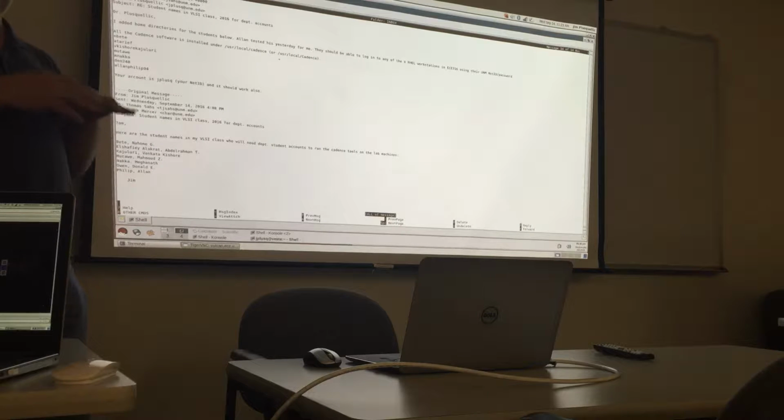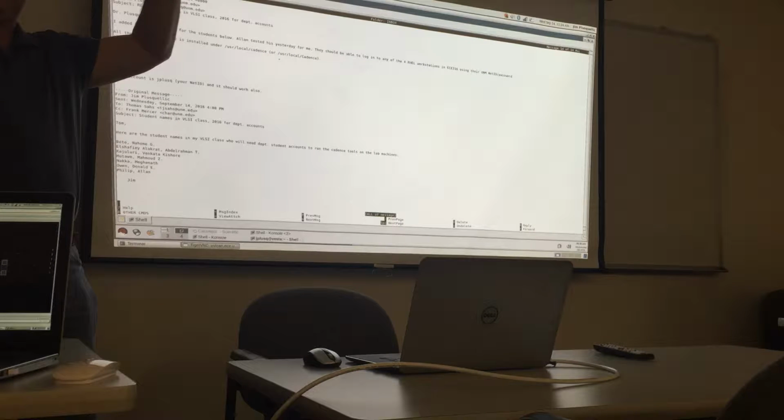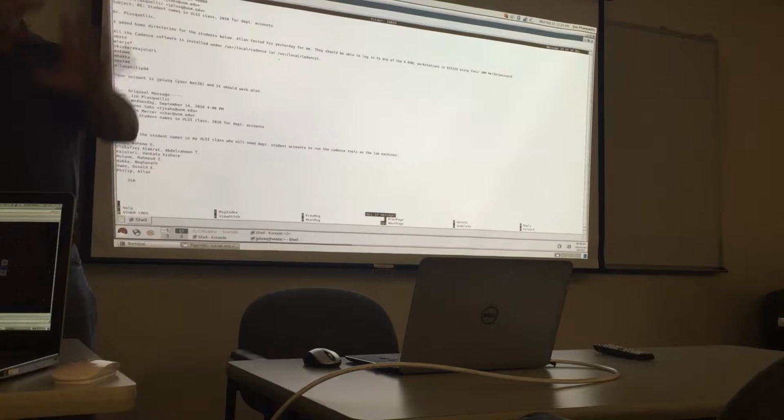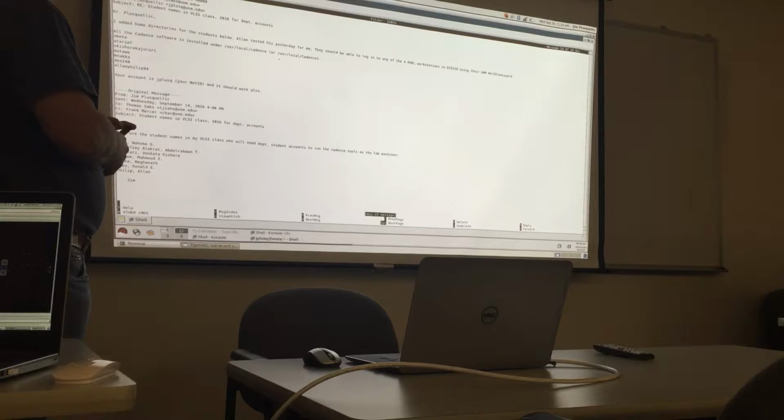If you want to connect that particular subdomain to something else, instead of connecting it to the top-level VDD bang and ground bang nodes, you could connect it to whatever the name was. That connection will inherit and propagate through all the elements connected below it, in the children, I should say. So it makes it a little easier.